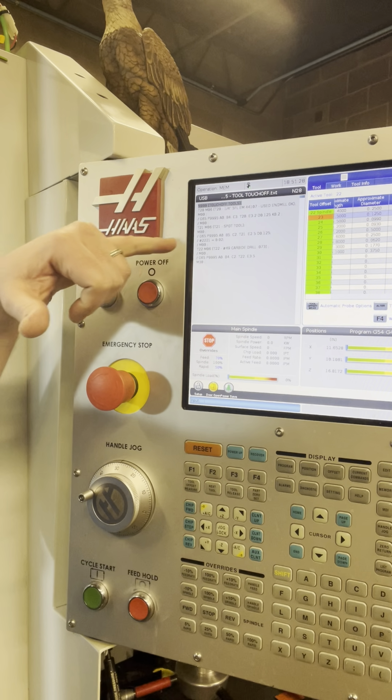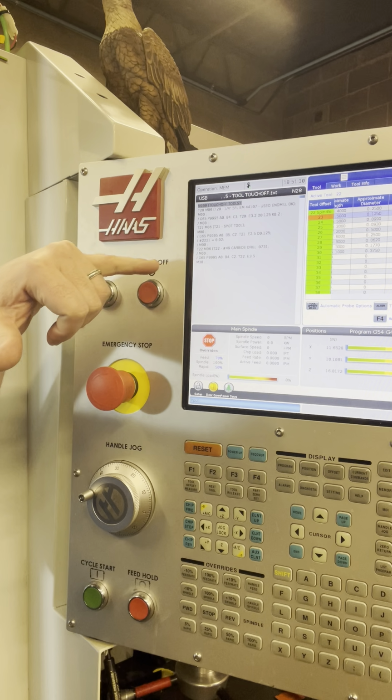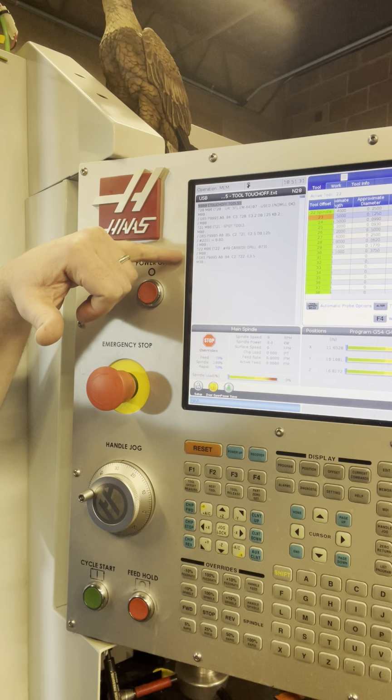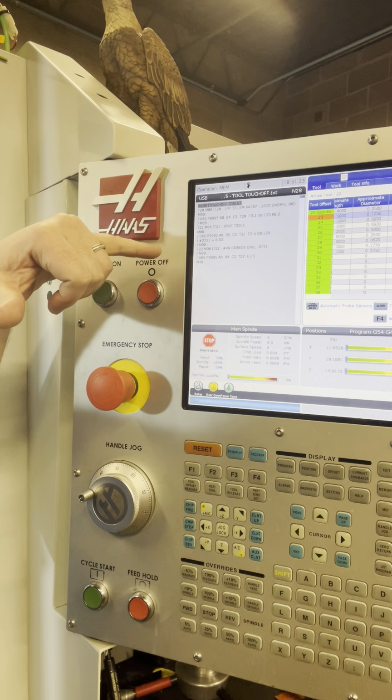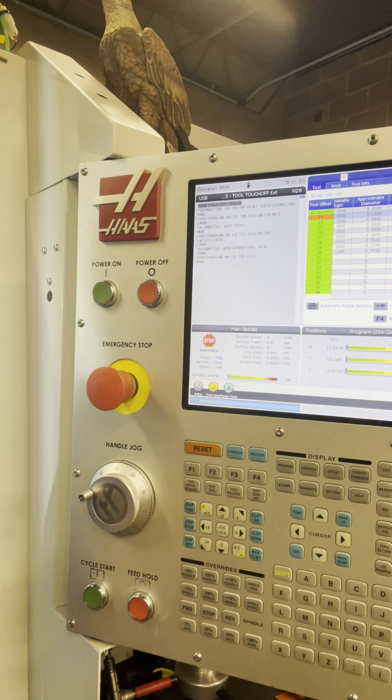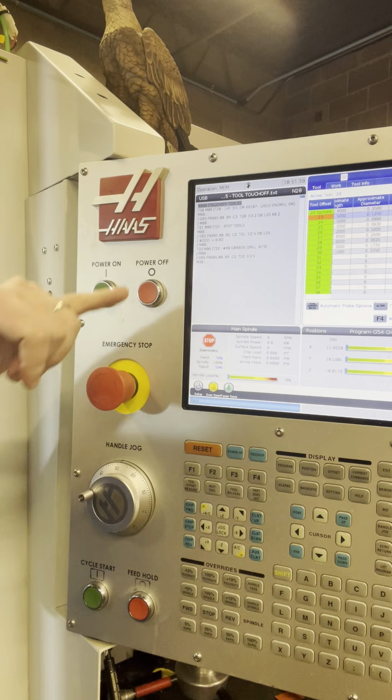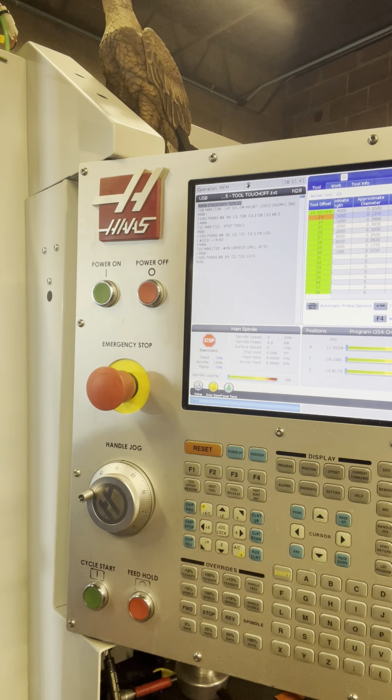The other thing would be putting the tool description down further, like after the M0, because when it does the tool change, it would highlight that then. So it's easy to see, all right, well, tool 21 is in the spindle, and I need to be putting in the spot tool. So it's highlighted in orange as it goes down. But yeah, you can play around with how you do this by what you want to do.